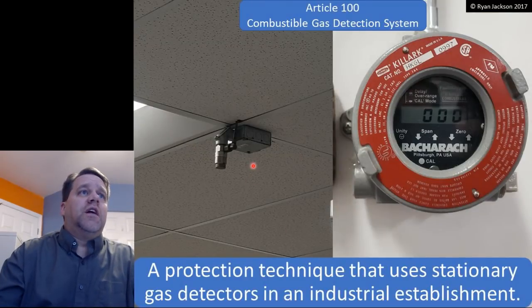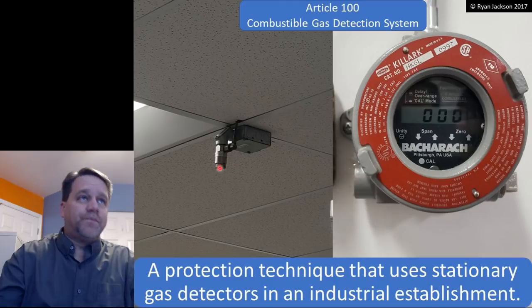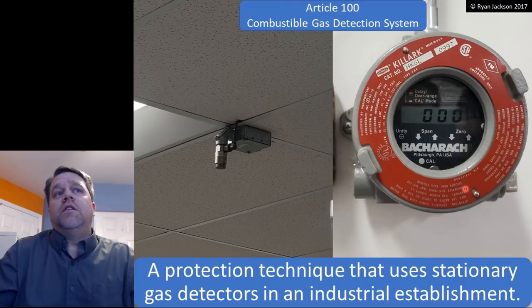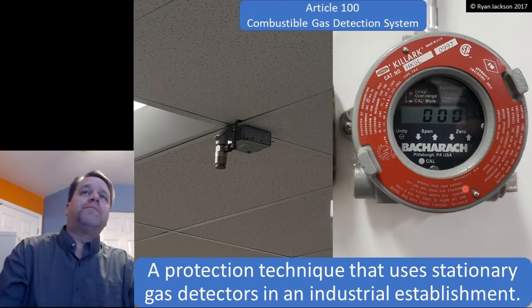This is a combustible gas detection system that is detecting a lighter than air gas, right? Hence the detection is up at the ceiling level. And then the indication equipment is here. So, a protection technique that uses stationary gas detectors in an industrial establishment.